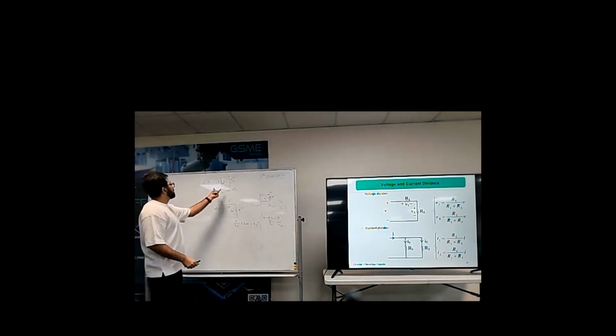How much is the equivalent of these two parallel resistors? The equivalent of 1 ohm and 10 ohm. Suppose I want to replace these two resistors with one resistor. How much is the value? 10 and 1, yeah. 10 over 11. Yeah, almost 0.9, which means almost 1 ohm. When you are paralleling two resistors, which one of them is much bigger than the other one, we can consider the parallel is only the smaller one. Almost 1 ohm.